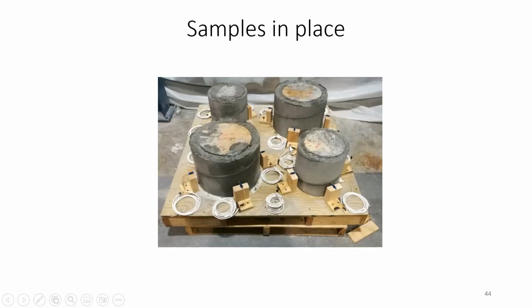Timber piles. We have also done work in the area of retrofitting timber piles. One of the big lessons we learned is that moisture variation in the timber pile can cause problems.